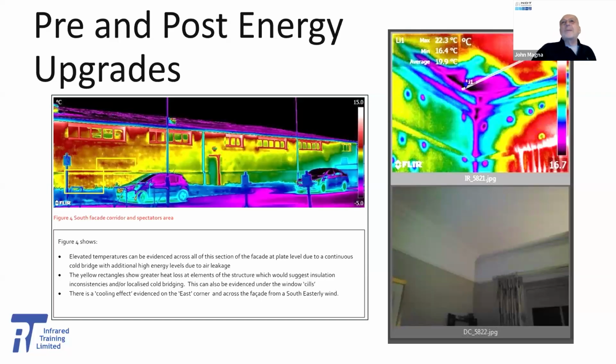Right-hand image was taken in the main bedroom of a certified passive house construction. The external top floor, corner to ceiling area was above the cot where a newborn baby was sleeping, which was being impacted by external air from the eaves, moving under some poorly installed attic insulation and causing what's often referred to as wind washing. This caused localized cooling of the surface of the ceiling by 5.9 degrees Celsius, which in turn led to a cooler corner compared to the rest of the bedroom.